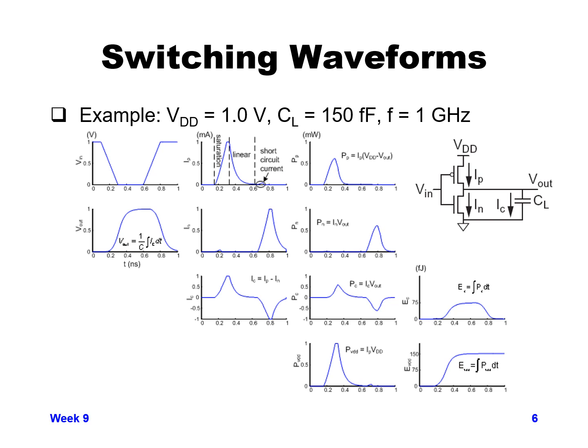And then finally, for the power consumed by VDD, you can see there's one big spike where the PMOS is turned on, and then there's a smaller spike where the PMOS has the short circuit current, but you can see there's no spike when the NMOS is turned on. And that's because you're not consuming any power from your power supply when you're discharging the capacitor.